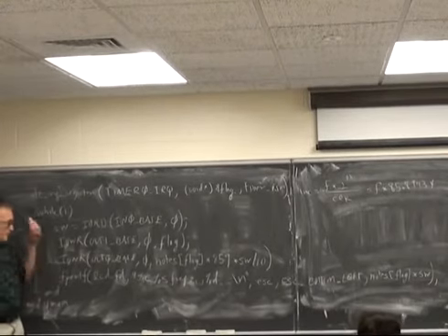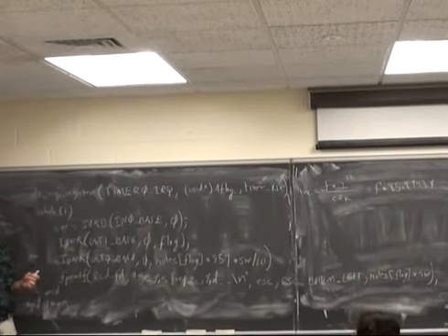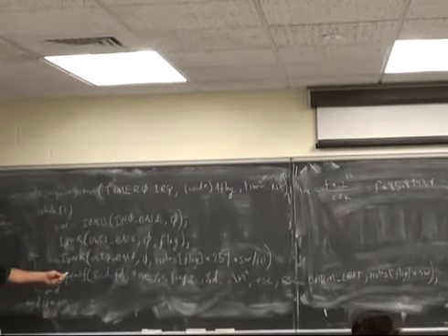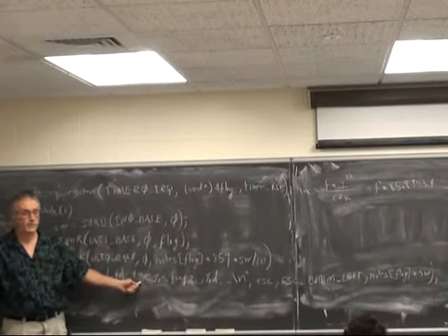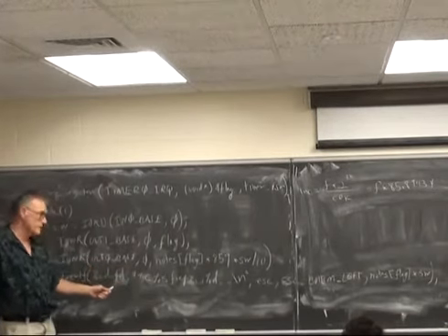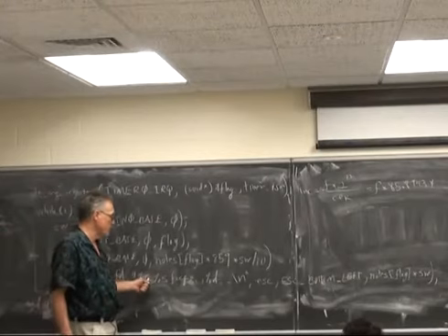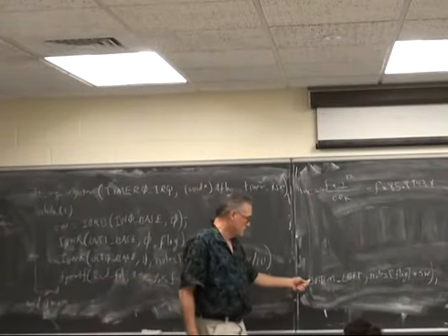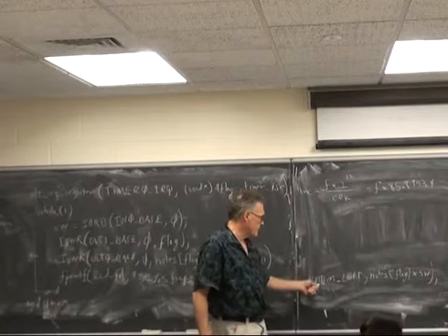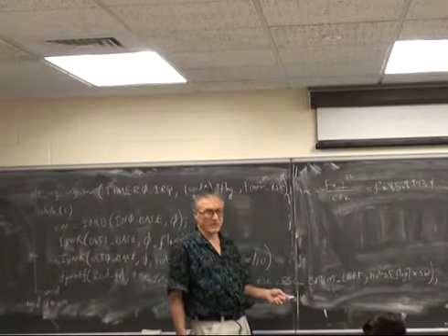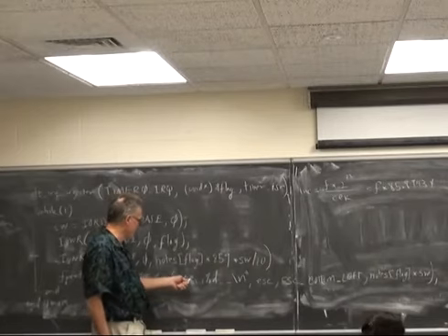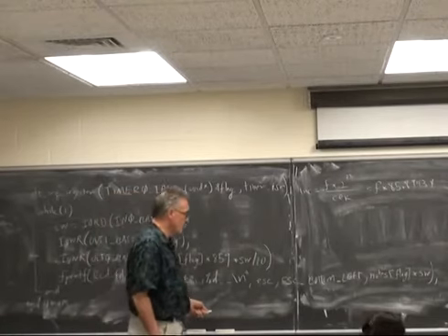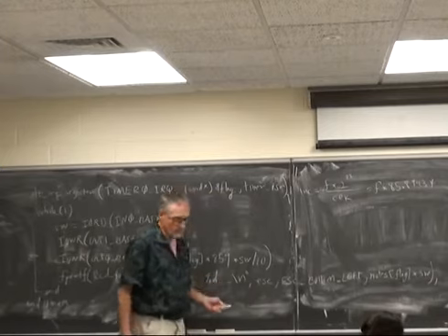The fprintf is a blocking function, and it takes about a millisecond per character to print this. So this string is going to take 1 plus however long this escape bottom left string was. I think it was about 4 characters. So that's 4, 5, 6, 7, 8, 9, 10, plus the conversion to int.